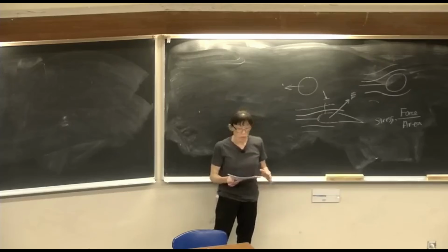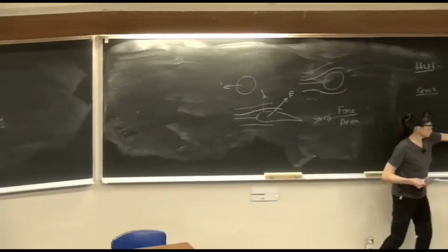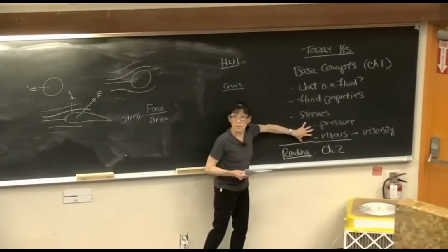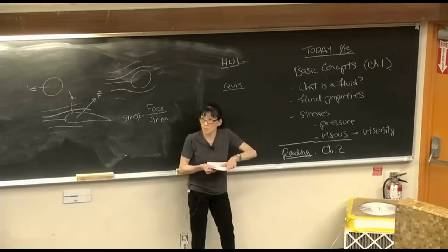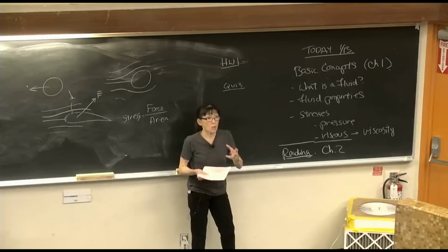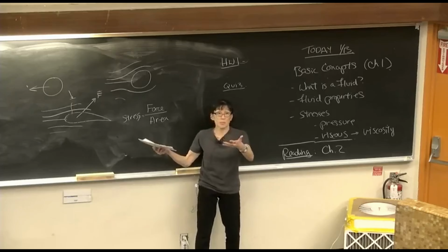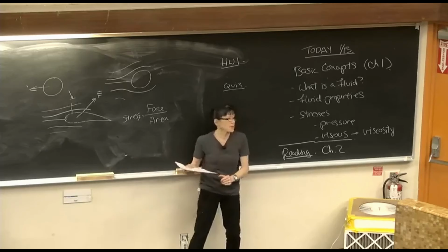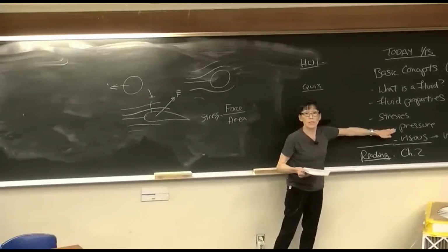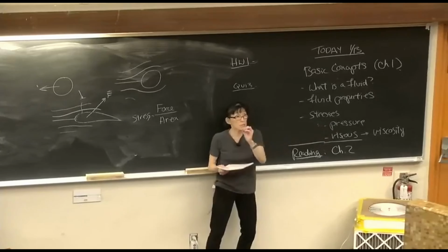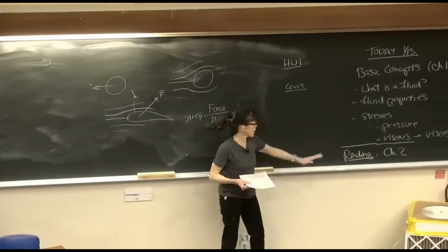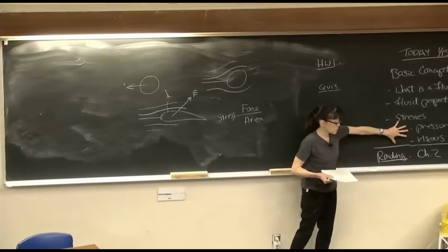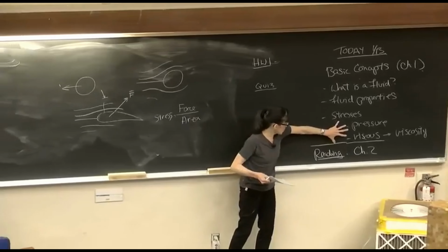So it's important to really understand this. Now, this viscous shear force is associated with relative motion. When you don't have relative motion, or if you don't have motion at all, for example, fluid at rest, which is what's here in this room, then all you're left with is pressure. That would be the stress occurring in the fluid. And that's where we're going to start off in Chapter 2. But in general, once the fluid starts in motion, we have to consider both.